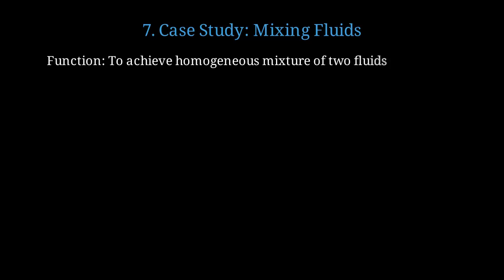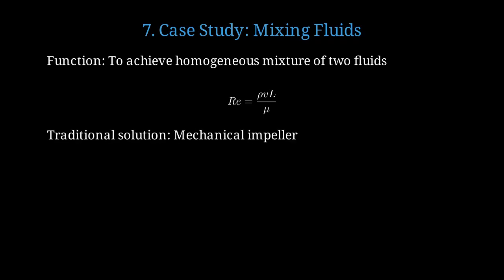Let us explore a detailed case study of mixing fluids to see function decomposition in action. The function is clear. Achieve a homogeneous mixture of two initially separated fluids. Reynolds number characterizes flow regime, relating inertial forces to viscous forces in the fluid. The traditional solution uses a mechanical impeller, rotating in the fluid to create turbulent mixing. An impeller shaft drives blades that create swirling flow patterns throughout the container.